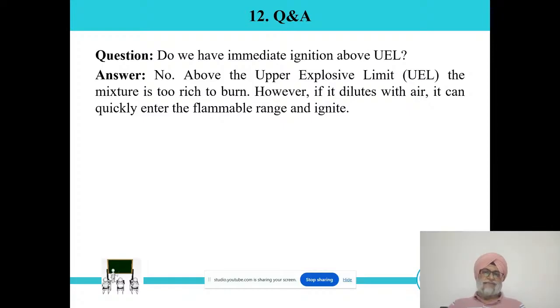Now, question number 12. Do we have immediate ignition above UEL? No, above the upper explosive limit. Normally, ignition is possible between the LEL, lower explosive limit, and UEL, upper explosive limit range. If concentration is above the upper explosive limit, when dispersion starts, it slowly spreads, and after some time that mixture will achieve a concentration below UEL, and at that time, if ignition is there, it will explode. So we can say if concentration is more than UEL, it's a delayed ignition only.